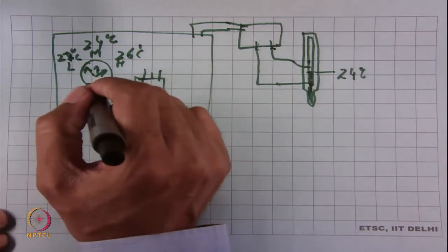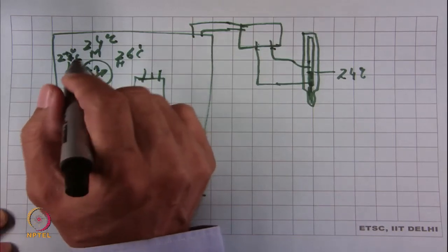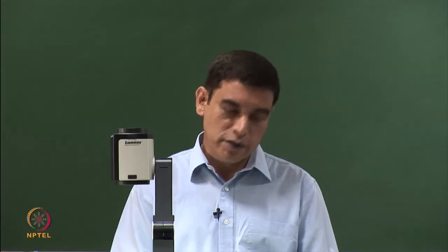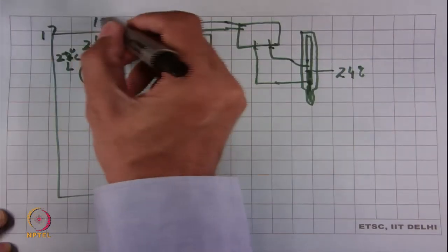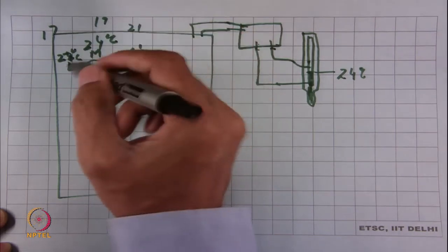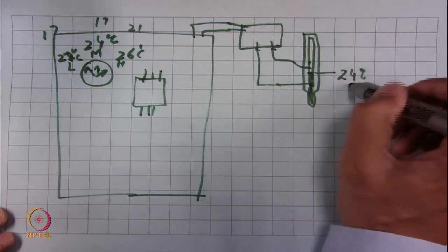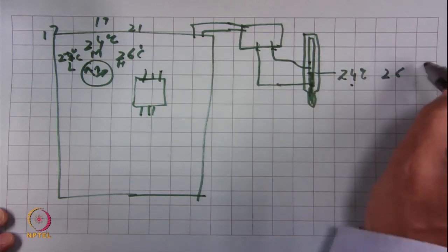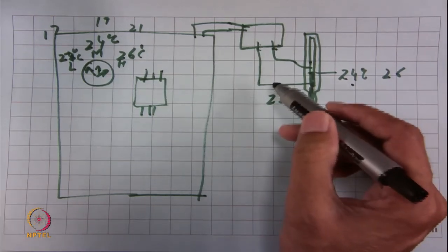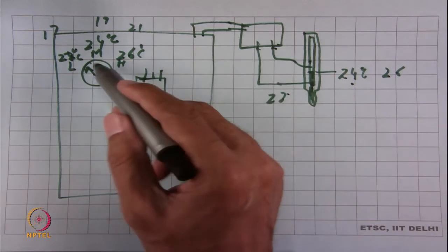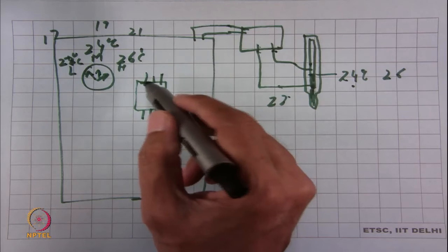At the time we were making these units, irrespective of whether it was for second AC or first AC, it was 22, 24, 26, and for heating conditions it was 17, 19 and 21. These were the conditions which were maintained. So there were 3 thermostats: one at 24, another at 26, and another at 22. Each of these would energize the pilot relay, and the pilot relay, depending on the rotary switch position, would control the temperature at 22, 24 or 26.